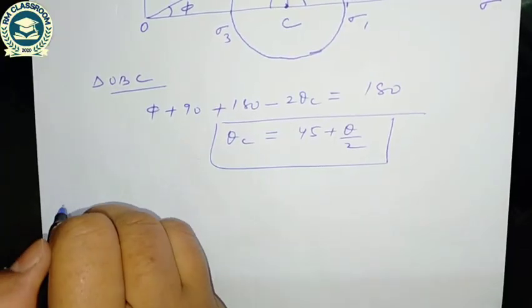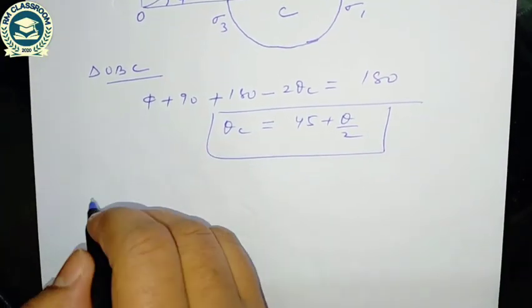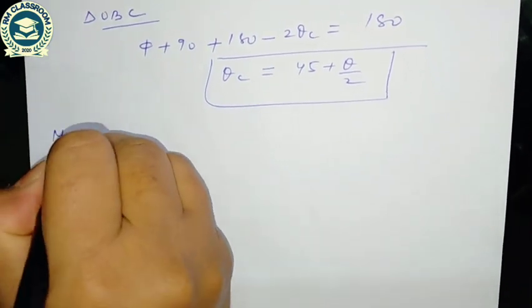After that I am going to show you the Mohr circle for clay and the Mohr circle for silt, and there is a relation between major principal stress, minor principal stress, cohesion and angle of internal friction that will be derived. And after that I will discuss what the Mohr failure envelope is, and what the Mohr-Coulomb criteria is. So after that I am going to draw the Mohr circle for clay.